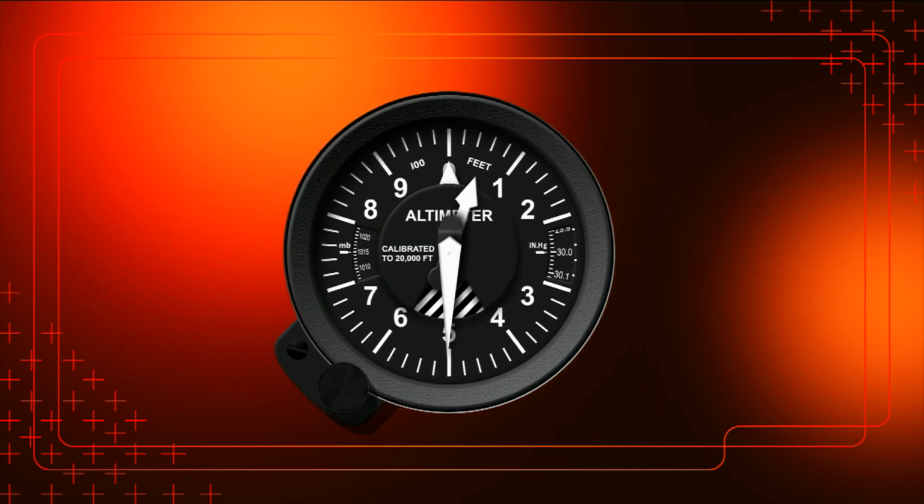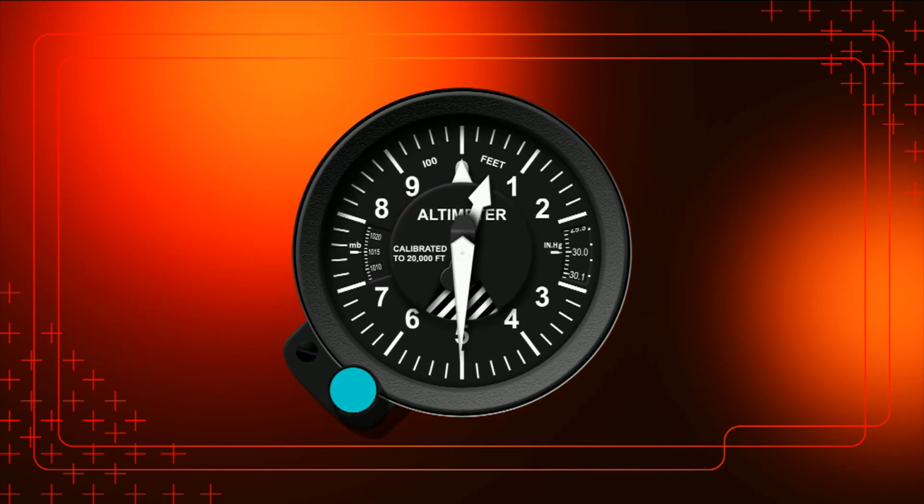In order to adjust the instrument to show this pressure reading, the pilot must adjust the knob on the instrument, which in turn adjusts the pressure scales within the instrument, and when set to the pressure reading given to the pilot by listening to the departure airport's ATIS, will provide the pilot with an accurate ground altitude reading for the departure airport.